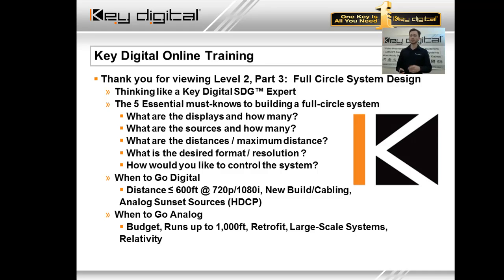It should be of high integrity. It should not have any patch bays, splicing, keystones, coupling, etc. You want to avoid that at all costs if possible, and certainly you want to disclose that information to Key Digital when we're building the system for you, because we want to deliver a system that's going to work for you.